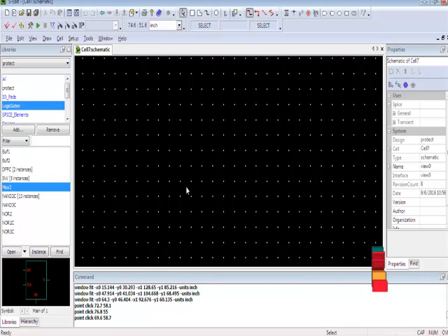After connecting the elements as per the circuit diagram, we save the file and select the corresponding library tools. After that, click the start simulation icon, then the window will start to run, and the corresponding output window will open, and also the corresponding timing window will open.